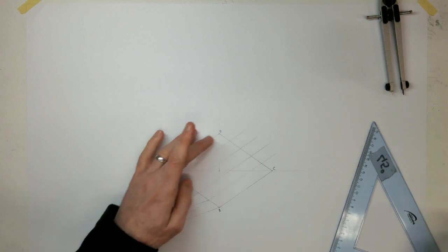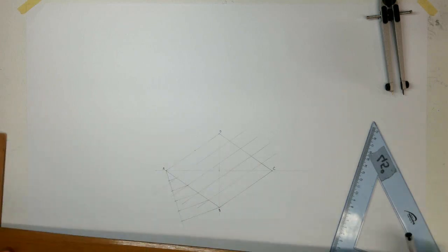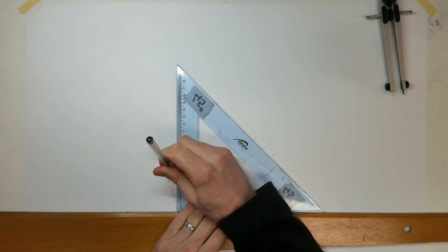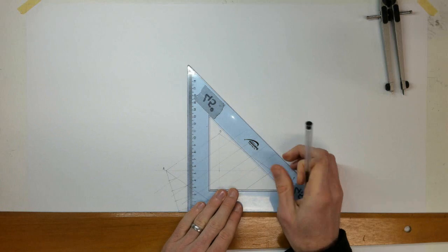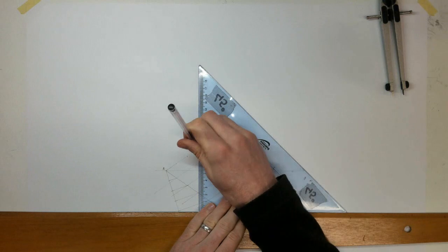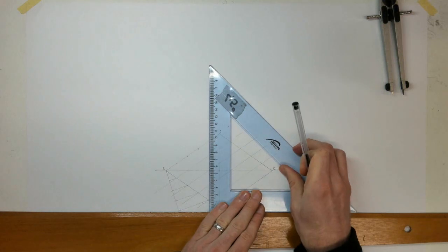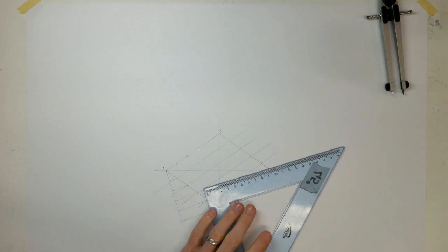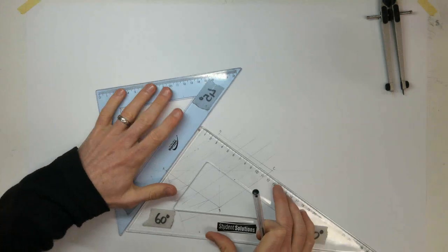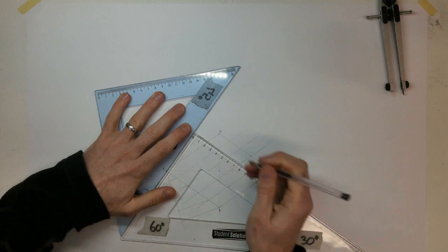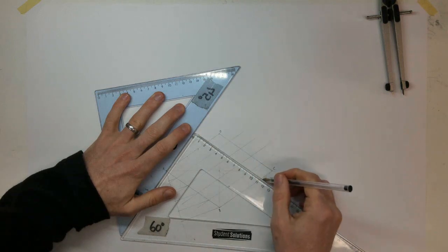Now I could divide up another line into equal parts, but just to do a little bit quicker, I can actually locate points just by finding them there directly above. So as I said, everything here is symmetrical. Now I can use my sliding set squares again. Extend them a little bit longer than I need to be.